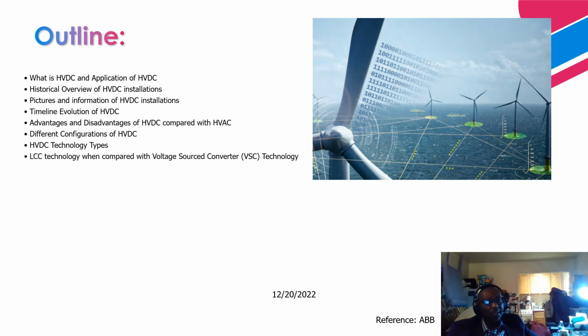So we'll talk about a comparison between the current source converters and voltage source converters. And in between that, there's something called capacitor commutated converters. That one was introduced to mitigate the drawbacks of the current source converters, the LCC type.